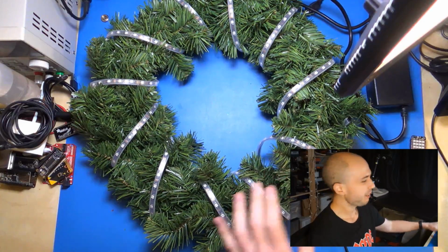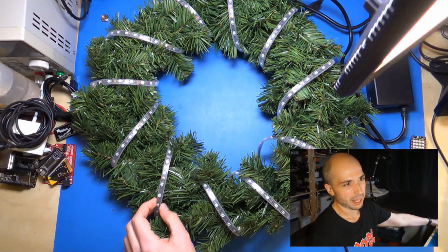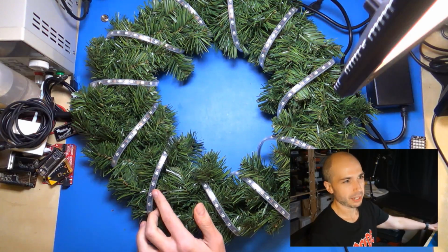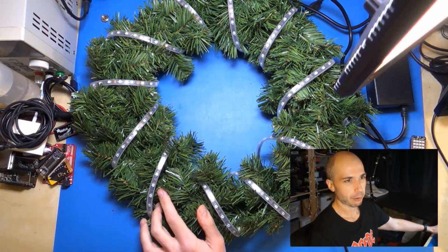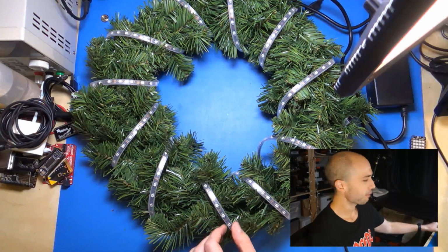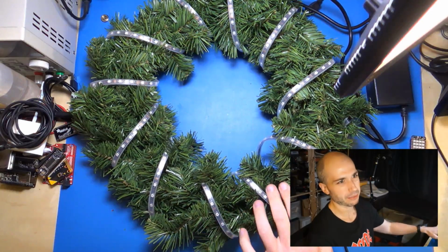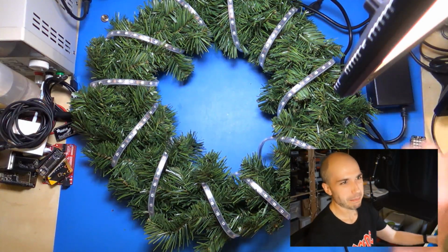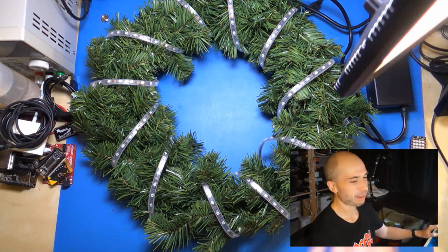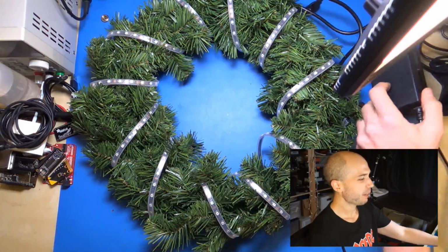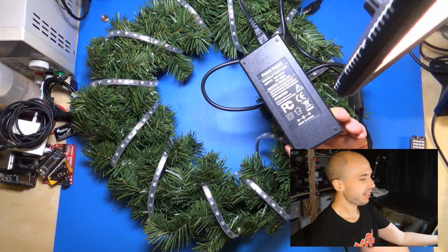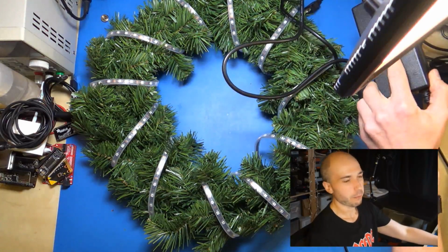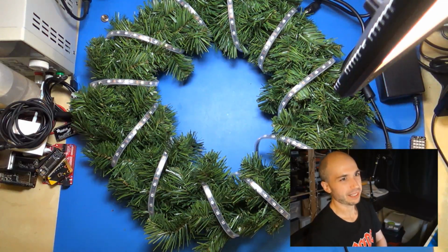This is a nice little decoration, and wrapped around it are NeoPixels. This is a strip, 4 meters of the 60 pixels per meter, which is a pretty dense NeoPixel. There are actually 210 NeoPixels around this wreath, which is a lot of pixels, it turns out. You might not need that many for your project, but it's what I had. Right here, kind of hidden, is a nice 5 volt 10 amp power supply, which we have in the shop. And when you're dealing with NeoPixels, you want a lot of power.